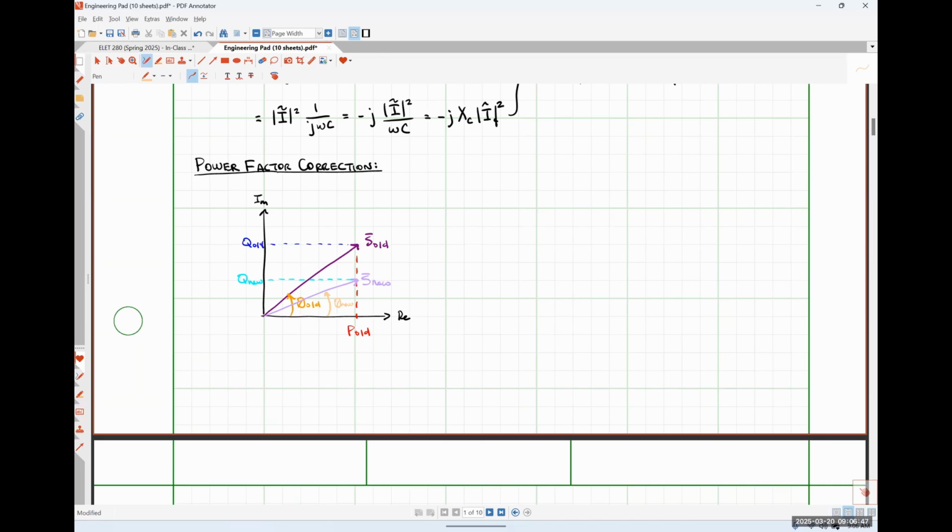Capacitors, absolutely right. So in order to correct the power factor in an industrial setting, we are going to put a big capacitor. Typically speaking, it will be in parallel with our voltage source, so that it'll compensate for any stray inductance in our transmission lines as well as the connected equipment, okay? So we're going to use a capacitor in parallel with our system in order to improve the power factor at which our system as a whole operates.